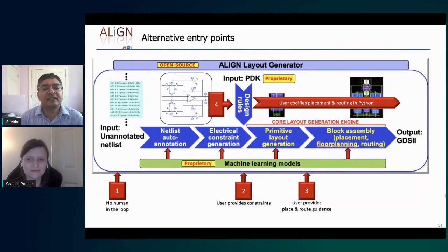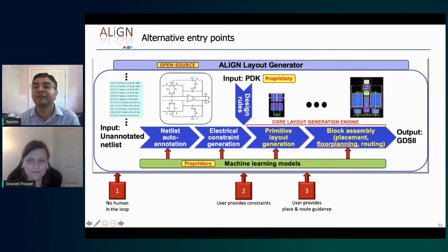Now, the interesting thing here is that in analog layout, typically area is not the biggest constraint. In fact, there are many scenarios where if you look at this picture, for instance, you can see that there's a lot of white space or black space over here. And this is enforced by the fact that you have symmetry requirements which require these blocks to be symmetrically placed, etc. So when you look at die photos of analog blocks, typically area is not the biggest constraint.